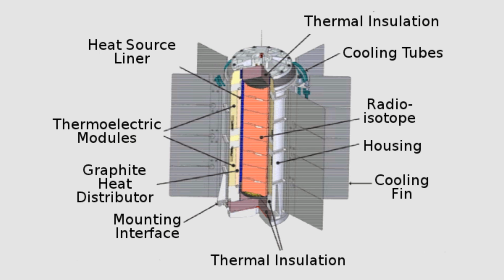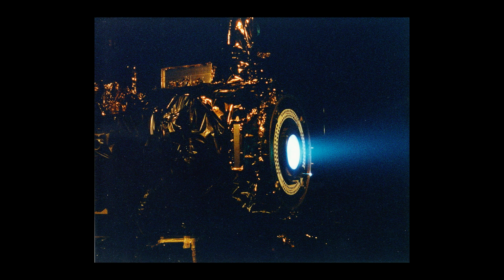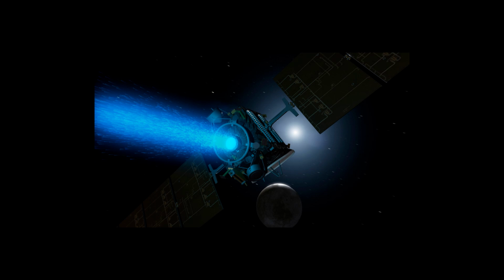And of course, you can use this electric energy to power an electric space propulsion system like an ion engine, or actually that's the most famous, but there are a few more electric space propulsion systems like arc jets, for example, but usually it's an ion engine. This is useful because, first of all, you have to get your energy from somewhere if you want to use electric space propulsion. And there's really only two effective ways, that's solar panels or RTG. And solar panels are only effective as long as you stay somewhere nearby the sun.